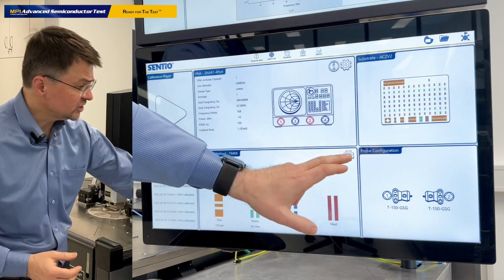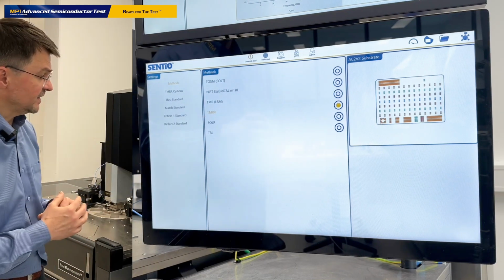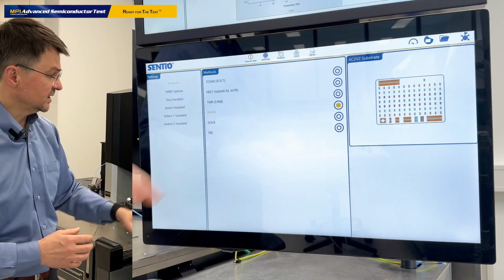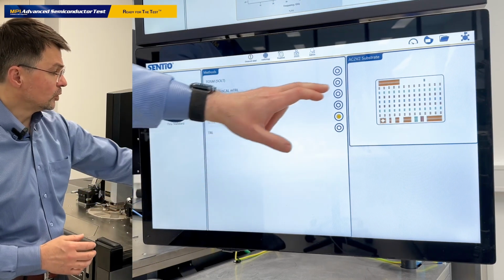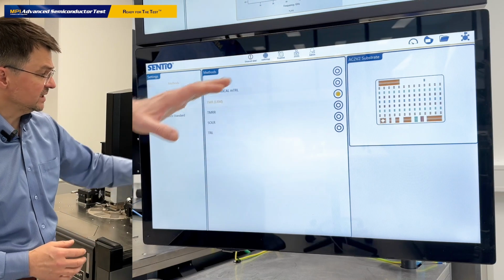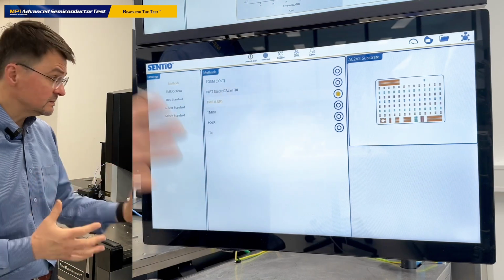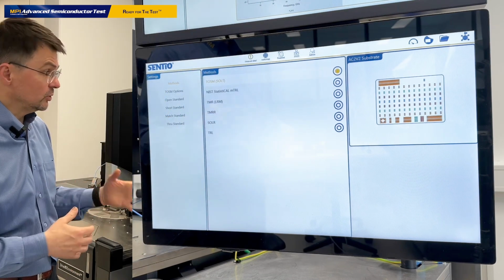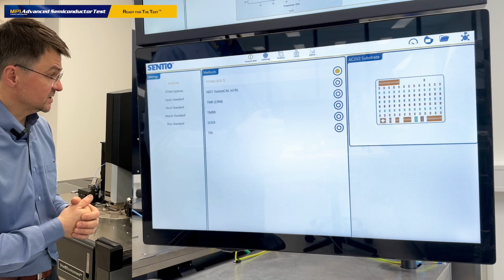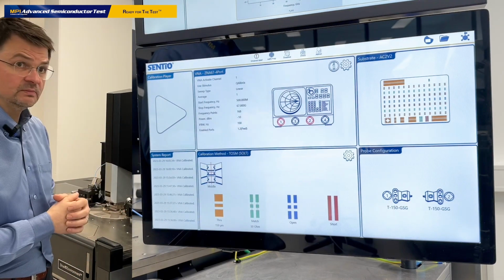We also can quickly change the calibration method, which is, as I said, through match reflect. We can select the SOLR calibration algorithm, we can select conventional TRL or a NIST statistical multi-line TRL to be executed from the Calibria Graphical User Interface, or a very simple calibration algorithm like through, open, short, and match, or SOLT, as everybody knows it. So that is as simple as that.